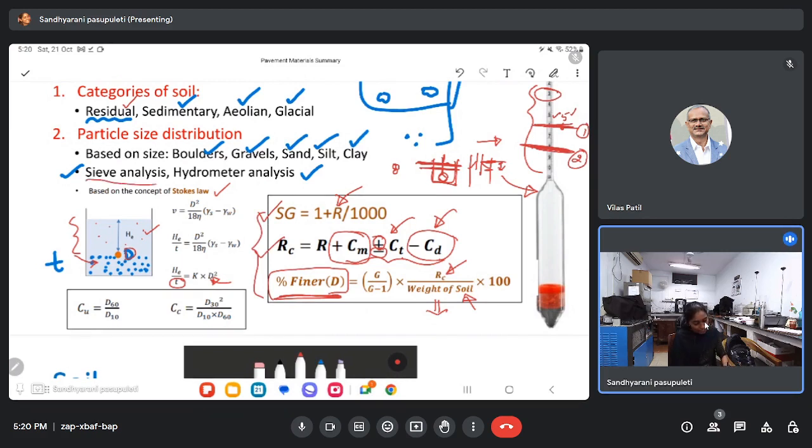From the sieve analysis on the coarse aggregates, which are greater than 75 microns, two outcomes would be the coefficient of uniformity Cu, which is D60 by D10, and also the coefficient of curvature Cc, which is D30 squared by D60 into D10. So for example, when I say D60 is equal to 2.3 mm, it means 60 percent of the particles have size lesser than 2.3 mm. In a similar way, we can understand the remaining sizes also.